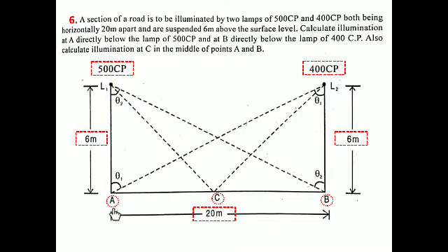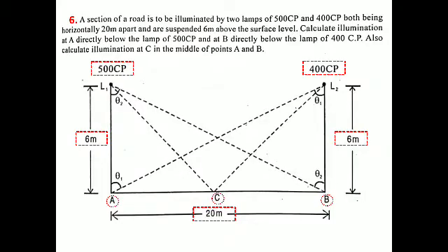So now we're going to calculate intensity at A point, B point and as well as C point. It is also a similar technique. You need to find these triangles. By this way you can find the diagonal and you can use the same formula here. Let's do one by one now. So first, I'm going to find the illumination at the point A. Point A is nothing but this location. To find this, you have to concentrate on this value and this value.